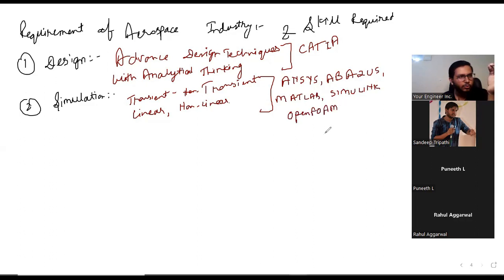Okay, today I'm giving you one more software where you can design airfoils. It's called DesignFoil. It's a free software on the internet. You can check DesignFoil. Simulation you can do. Like NACA series, NACA 4412, 3312, 3324, whatever. You can play with that and you can see how things are happening, where the center of pressure is, where the aerodynamic center is. That's called a simulation.